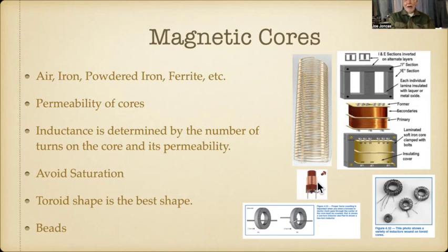Now here's a ferrite core. This little guy right here has this coil right here, but up the center of it is a hunk of ferrite, and it has a slot in it. Many of them are just like a six-sided hole, and you've got a little tool you can stick in there, and it's threaded, and you can screw the ferrite in and out and change the inductance of this.